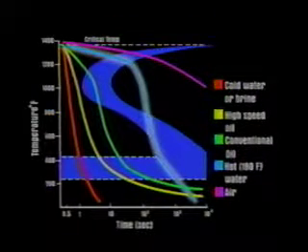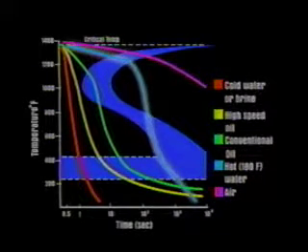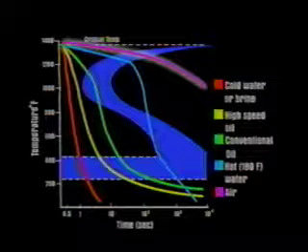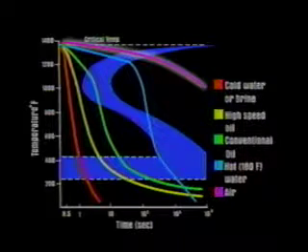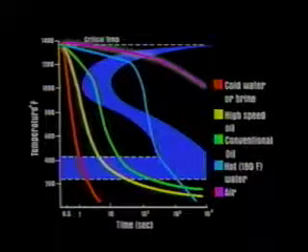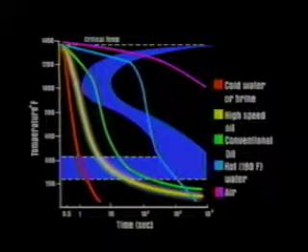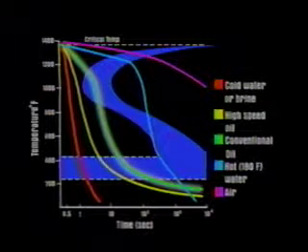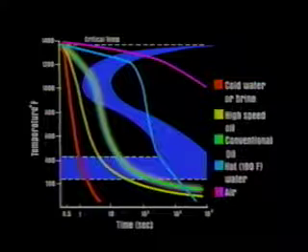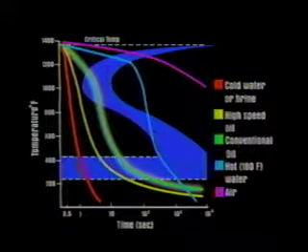If hot water is selected, the formation of undesirable pearlite in addition to the formation of martensite will be possible. If the steel is simply placed in air and allowed to cool, the desired martensite will not be formed. Instead, a pearlitic structure will be formed which has a low hardness and strength. Other quenchants, such as fast oils or slow quench oils, will produce different cooling rates, which will also affect the steel's ability to achieve the desired microstructure during the quenching process.